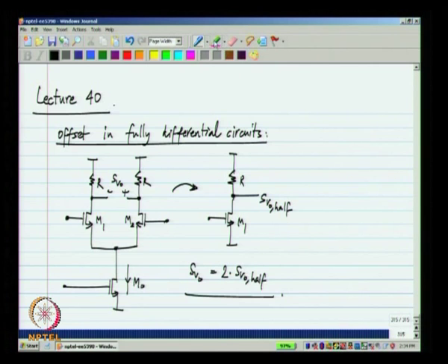Okay. Now, as I emphasized, the noise current of this resistor causes a certain output voltage here and there, and similarly this resistor will cause some voltage here and there and so on, but the net result is that you take the half circuit, do its own noise analysis and double the spectral density to get the output noise spectral density in a fully differential circuit. Okay. Similarly,